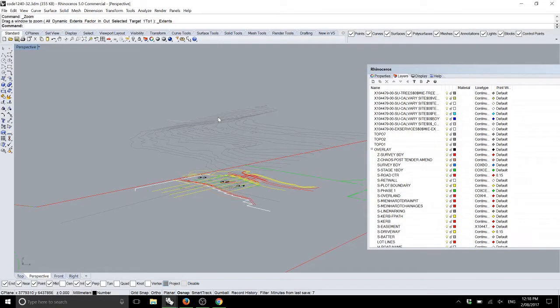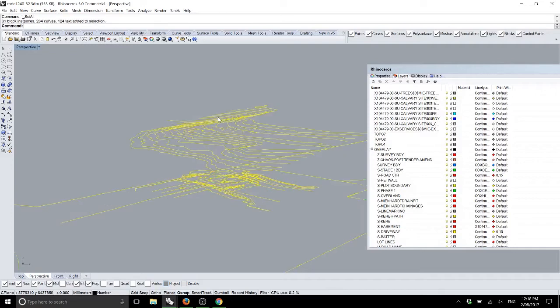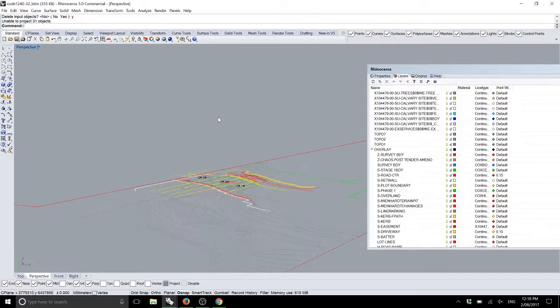Okay? Because what happens is when they go to start drawing lines on it, it'll snap to the 3D points on it, and you start getting these lines that jump about. If they measure the length of those lines, it's going to be longer than what they're intending it to be in 2D. So they panic and flatten everything. They grab everything and they flatten it. For example, they would grab this whole thing, they would go project to C-plane, and they're good, right? They can now work in 2D, they don't care.